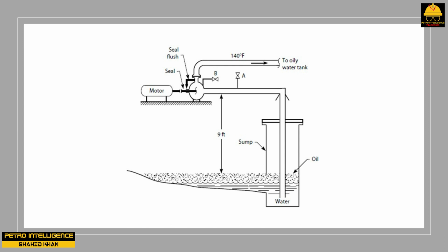When the pump is shut down, the space between the seal faces is filled with the fluid in the suction of the pump. However, if the pressure at the suction of the pump is below atmospheric pressure, then air is drawn through the seal faces and into the suction of the pump. This air displaces the water in the pump's case and, with time, causes the pump to lose its prime.